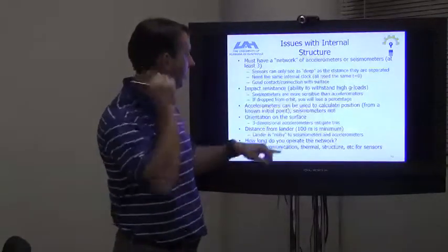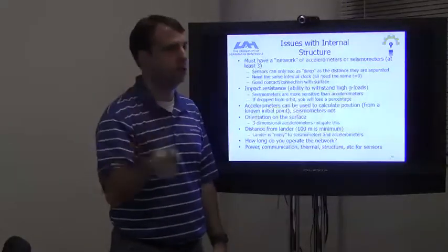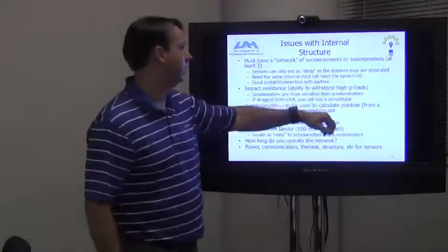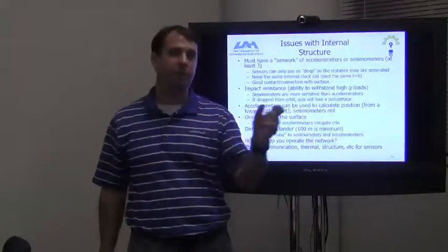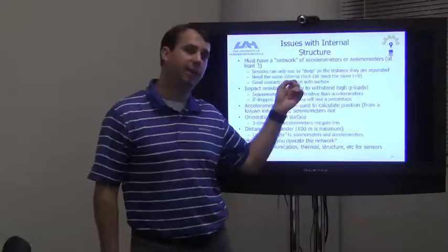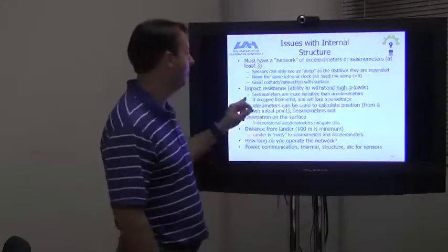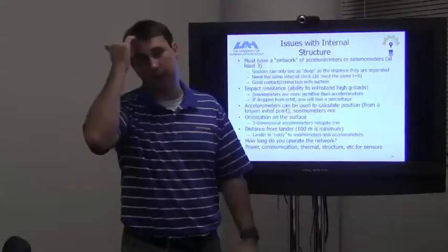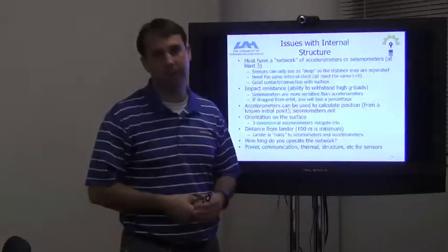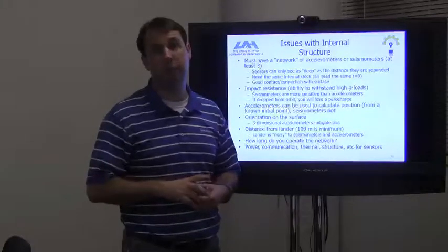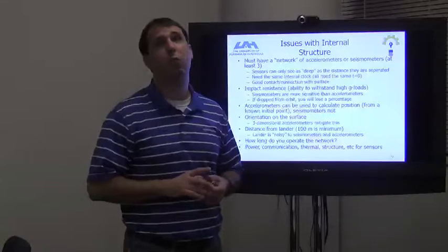Impact resistance, ability to withstand high G loads. Seismometers, not so good. Seismometers are more sensitive than accelerometers. They are better at measuring seismic activity. Don't get me wrong, seismometers are built for that. Accelerometers really aren't built for that, but accelerometers can measure seismic activity. They can measure the vibrations. Seismometers are just a little bit better. But an accelerometer can withstand really, really high Gs.